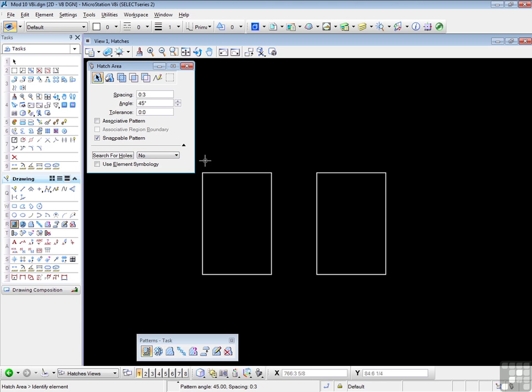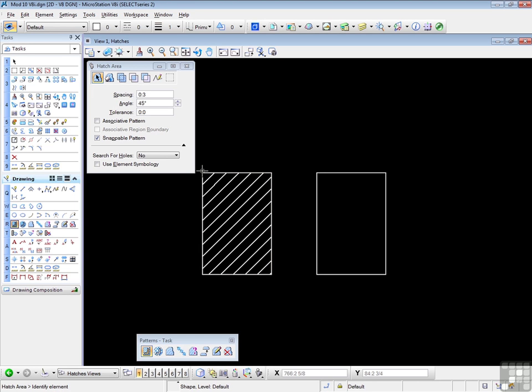Everything is set, and it's just a matter of choosing the appropriate option in the tool settings window. Right now I have element selected as the method to place the hatch, and we'll stay with that for the moment. Since we do have a block element in the drawing, it makes sense to use that. So we need to select the element, and the prompt is saying accept at pattern intersection point. This gives you the option to actually locate where the first of the hatch lines will actually run through. I'm going to snap to this top corner and left click, and my hatch is placed.